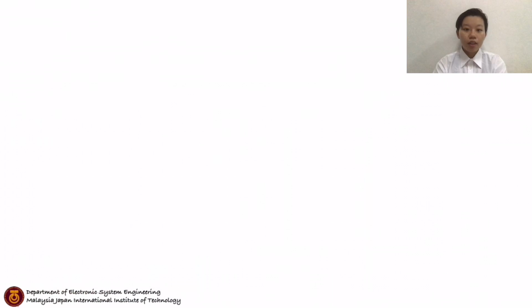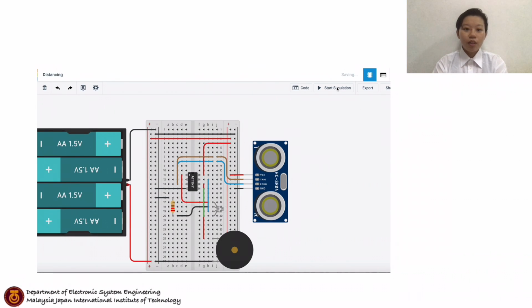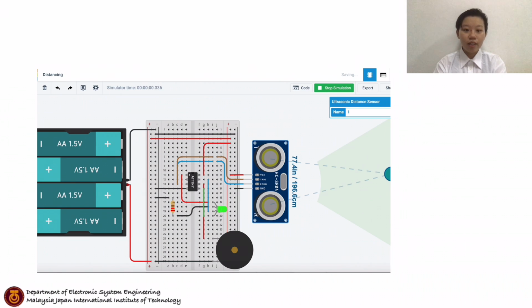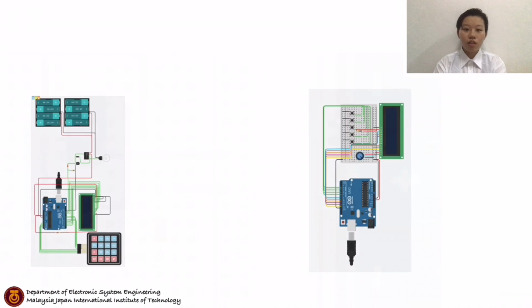In the second module, which is the Social Distancing Module, an ultrasonic sensor is used as the interpersonal distance detector connected to the 8-bit microcontroller ATtiny. The indicators in this module are an RGB LED and a piezo buzzer. When the distance of the next voter is too close to the default distance, the piezo buzzer will sound and the RGB LED will turn from green to red as a caution to the voters.